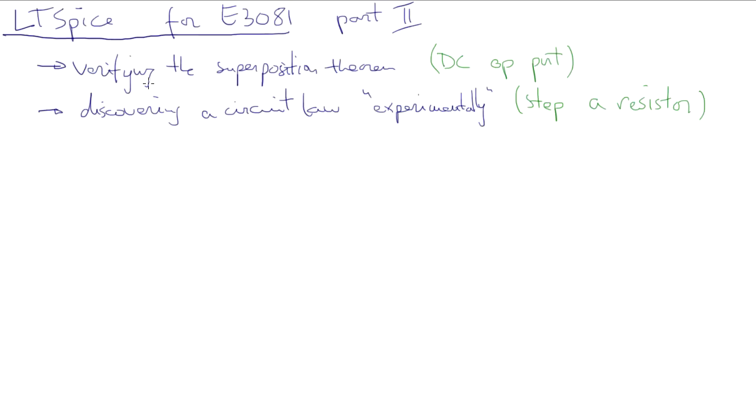In this part, we will learn how to verify the superposition theorem by using the dissipated function of LTSpice. And we'll also learn how to discover a circuit law, "experimentally", because we will be using a simulator, by stepping a resistor and plotting the values.